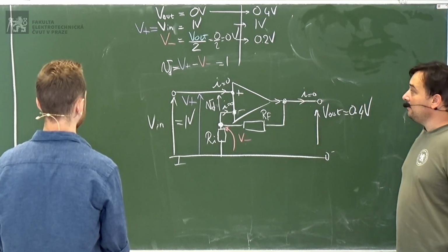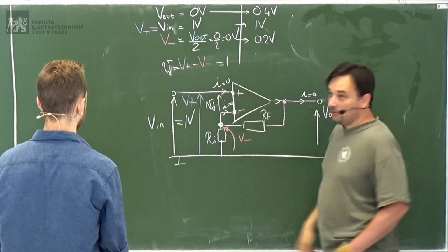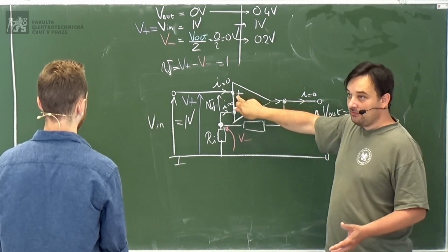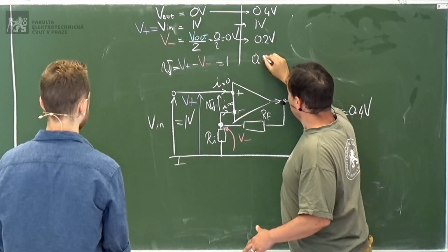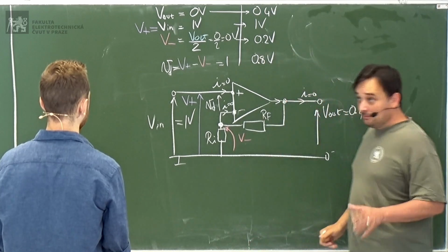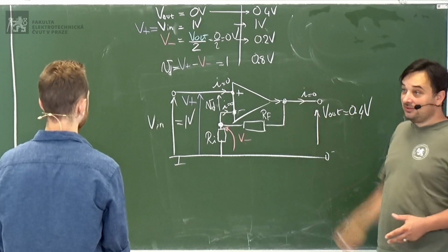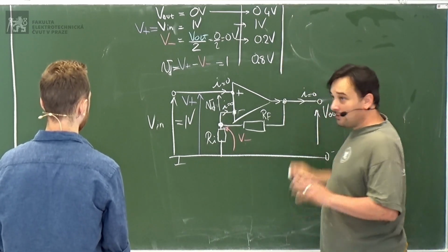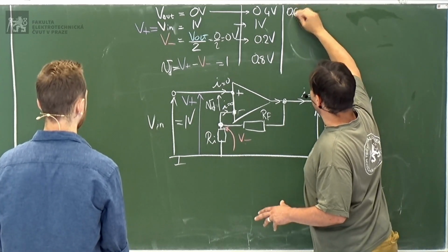Now let's calculate the difference. V plus is 1 volt, always the same. At the positive input, we have 1 volt. So it's 1 minus 0.2, exactly, so 0.8. Good, we are warming up the oven. But it's not enough because the difference is still not 0, so we push it more. It says, okay, 0.4 is fine, but not enough. Let's go for 0.6 volts.